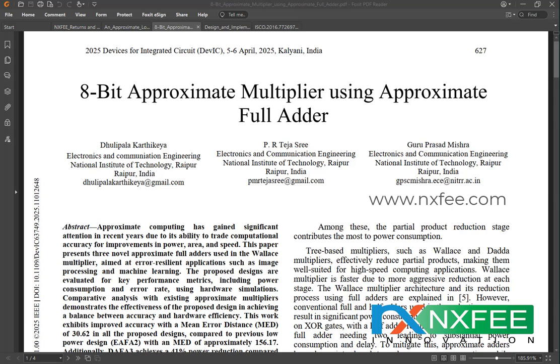The existing examples, RAFA1 and RAFA2 based reversible adder designs, are used for comparison to highlight the improvement in logic size and error rate. Additionally, the proposed adder is used to build reversible 4:2, 5:2 and 7:2 compressors and an approximate multiplier architecture, allowing evaluation of how the new full adder behaves inside higher order arithmetic blocks.